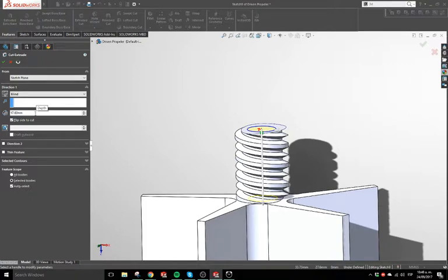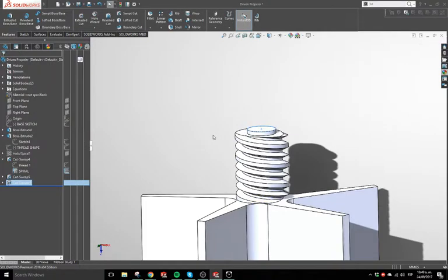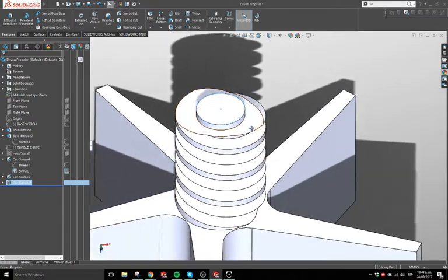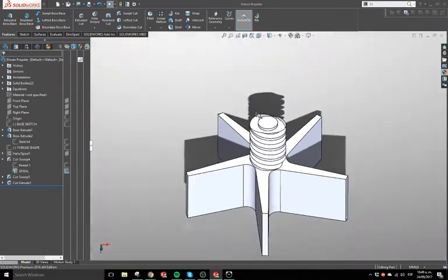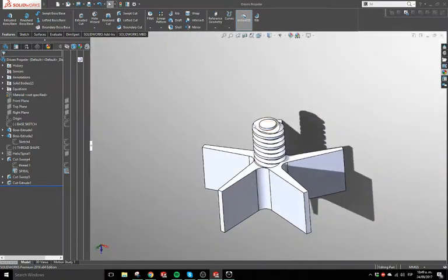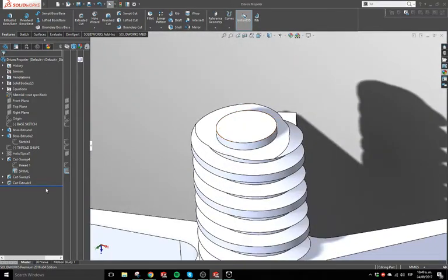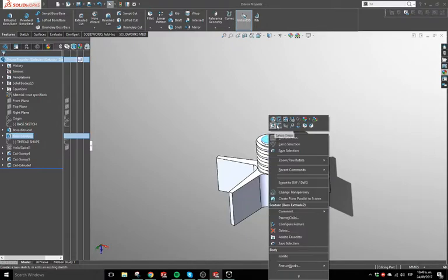It's like 1 millimeter. Since I chose to cut outside, what it keeps is what's inside the closed contour, and it cuts everything else in the direction of the generatrix vector, which is the vector normal to the plane where I did the sketch.